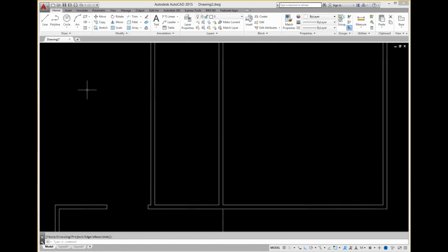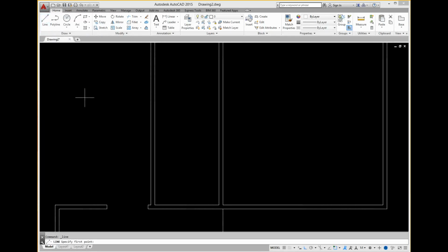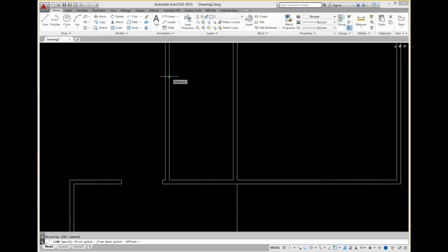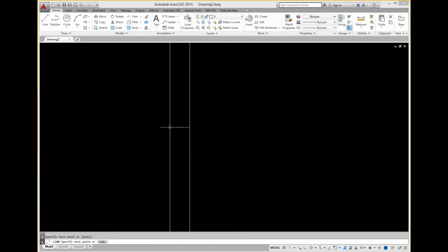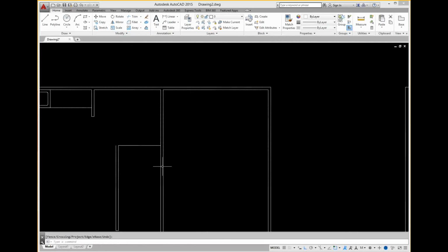And we have 2 more of those. So let's click on the line again, hold down the shift, right click, from, on the inside of this corner, hover over the midpoint icon, type 3 foot 0.5, enter, and then click on this perpendicular icon, enter, offset 32, enter, click here and above, enter, trim, enter immediately, and then 1 more.